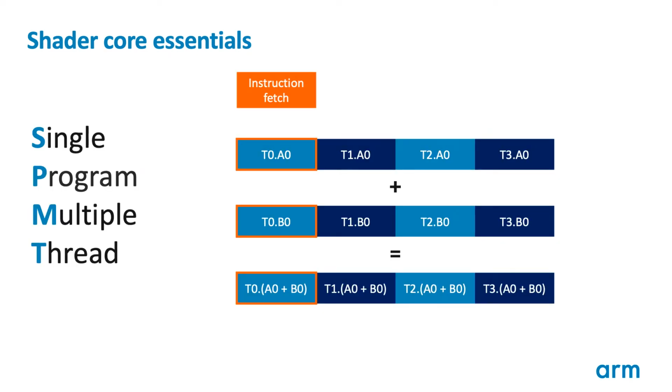We like the vector hardware of SIMD instructions, as they amortize control overheads, but the SIMD instructions themselves can be problematic. SIMD exposes vector instructions to each thread. So, the program being run must contain a vectorizable problem to take advantage of the hardware. Some aspects of graphic shaders are certainly SIMD friendly. We have X, Y, Z, W vector data, and RGBA color data. But modern graphic shaders are using increasing amounts of code which cannot pack out to Vector 4 hardware units.